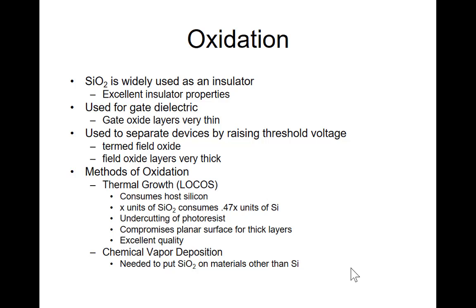You have your transistor, you have the active, and you have a gate. The intersection is a thin oxide layer. And that one, like we said, is on the order of 10 nanometers, depending on which process. Maybe 10, 15 nanometers, or maybe 5, 6 nanometers, right? It's very thin.